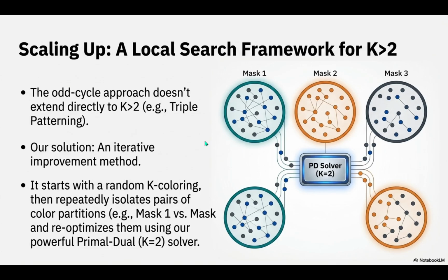It really does. So they defined the objective function to minimize this weighted sum of EBL area and stitch cost. You have the EBL cost, alpha, and the stitch cost, beta. And in the real world, the cost of running that EBL machine is just vastly higher. Oh, much, much higher. So the weight factor alpha is set way higher than beta. This tells the mathematical solver to always try to avoid EBL first. It will only insert a stitch if that stitch prevents an even more expensive use of EBL.